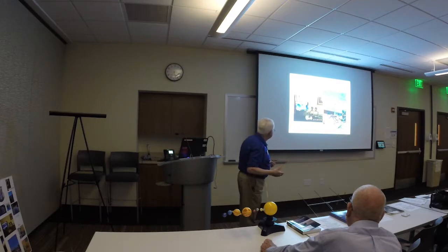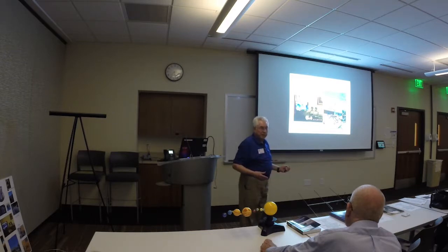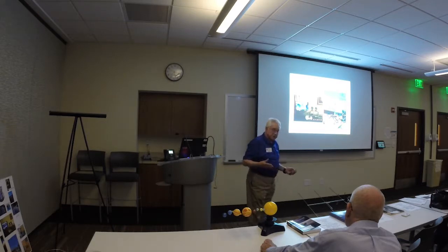And this is a Kenwood TS-2000 tied with the rotor controller, an interface box to allow the computer to control the rotor and the computer to control the radio. The program in the white area that you see here is SatPC32, which is available from AMSAT, by the way, for 50 bucks. It allows you to select the satellites that you want to track, and you can track up to 12 satellites simultaneously with all of their views.